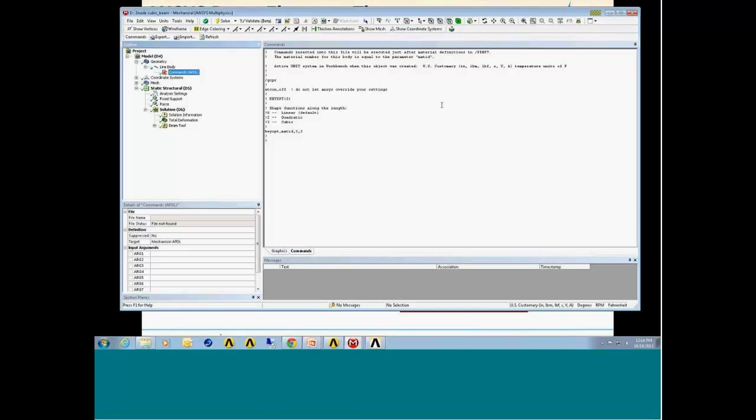You'll notice a couple of lines I've included in this command block as well. I first set /GOPR, which essentially says let ANSYS echo the information that I'm including in this command block in my solution information folder, so I can verify that I did indeed include this key option setting. Then I also set ET_CON, off, which says don't allow ANSYS to automatically adjust the key options.